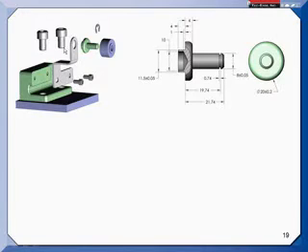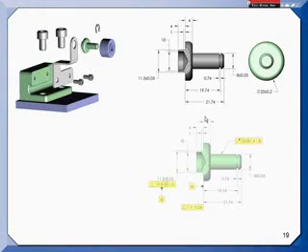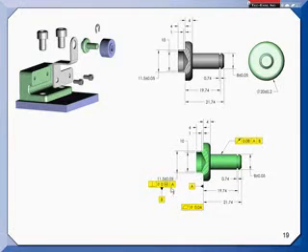The stud gets riveted onto this bracket. So when I rivet it down, it draws it up against this surface right here, and it centers up on this 11.5 diameter. So the most degrees of freedom will be constrained by that surface. So I'll make that my primary datum feature. I'll make this diameter my secondary datum feature. And yes, this is an important diameter. I'm going to have a good control on it and a tight size tolerance because there's a good fit to the roller. But I'm not going to make this a datum feature.